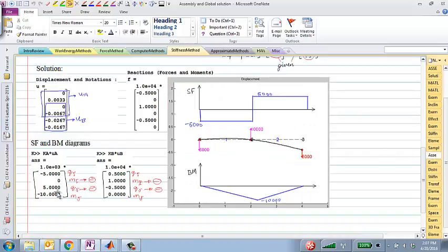Right. So for the frame or the beam problems, what I expect you to do is to tell me how you got the local element degrees of freedom, pick them out, calculate, and transform them if needed. For beam problems, you of course don't need to transform them, everything is horizontal. K element local would be the same in the local or the global coordinates. Pre-multiply Ka times Ua, get Qa, and then interpret those quantities in the correct way to draw these shear force and bending moment diagrams. Okay. All right.